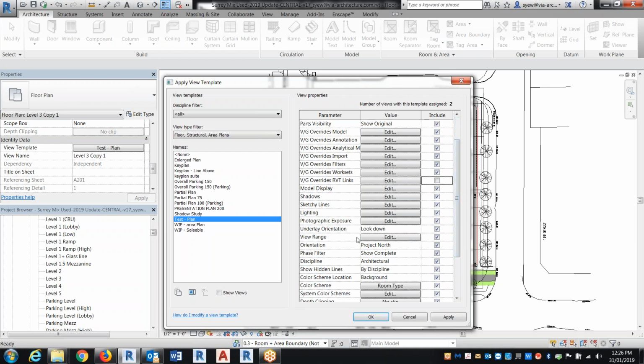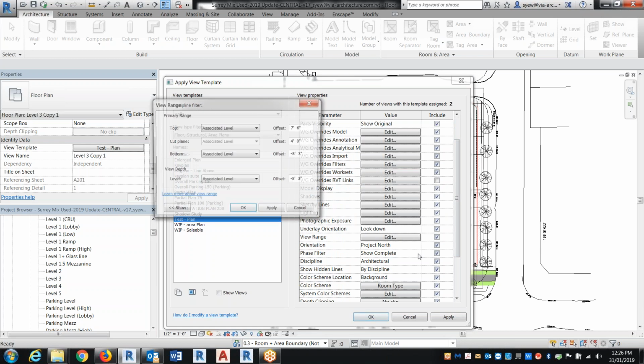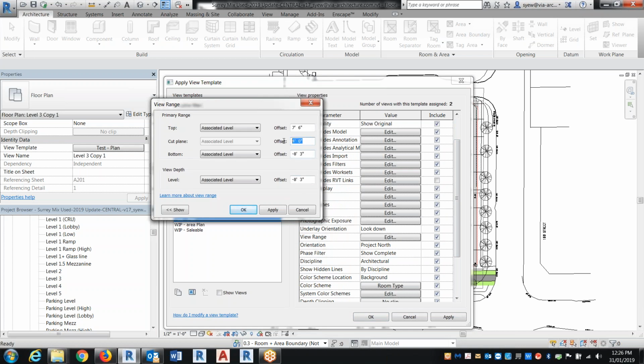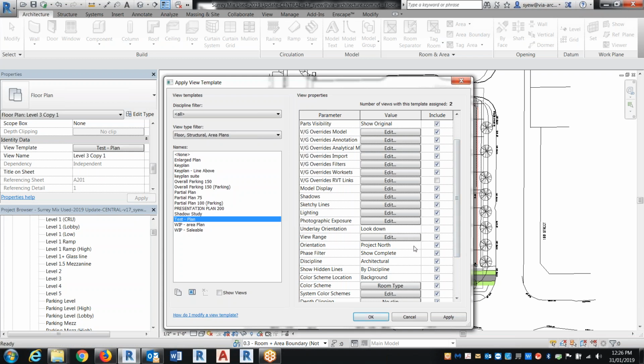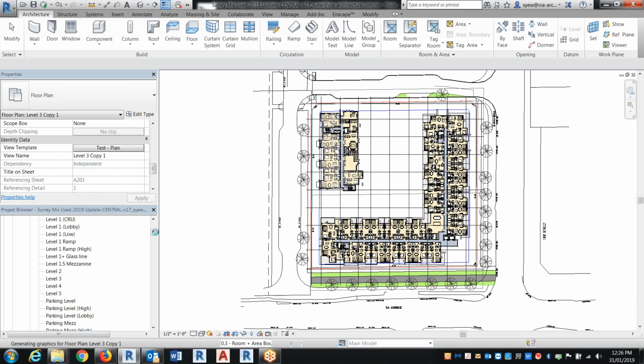And the other thing is the view range. View range is very tricky, because by default, you can say it's 4 feet. This one I would just say -1, -1. Now, in certain cases, you're going to have a double height scenario where one height is going to be different than the other. So this is where I tell people, turn it off if you want to, right? So that each of those particular views that you're working on has its own setting. But for now, I'm just going to keep it simple, just keep everything the same, okay? And say okay.